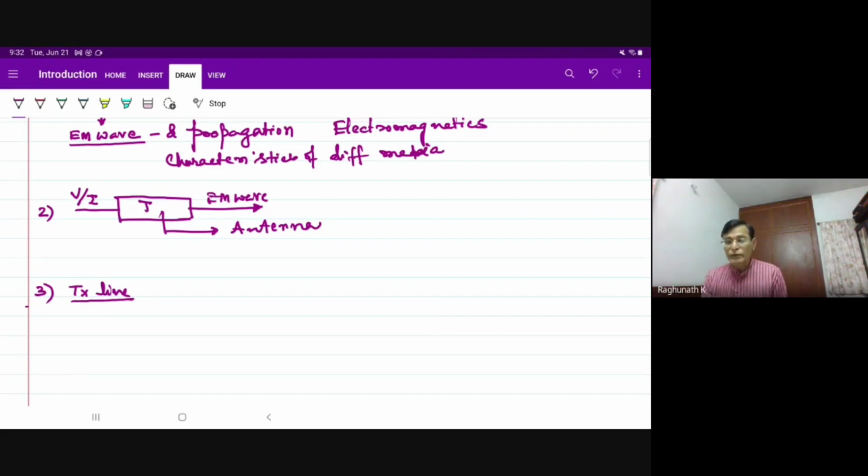The bandwidth is one of the most important things for us. The bandwidth and the attenuation constant, as well as phase shift constant, the required values of these things are different in different applications. If it is a sensitive application, I need to have attenuation constant to be very small, and the line should be non-distorting.